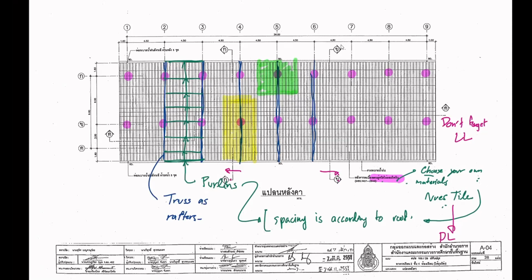And when the roof is concrete, you have to use something different, because the live load is going to be different. They expect you to use the roof. If it's concrete, the live load that you use for design is not going to be the same as for a typical roof with tiles.